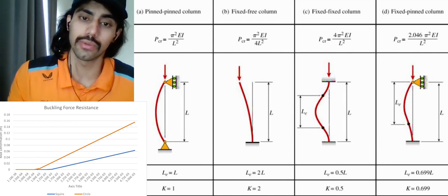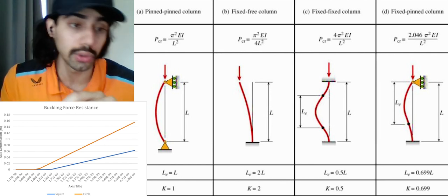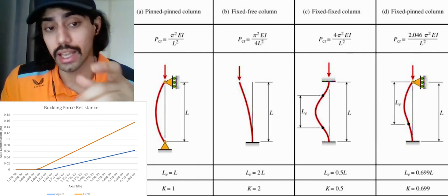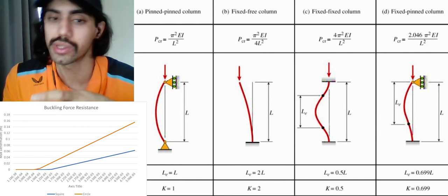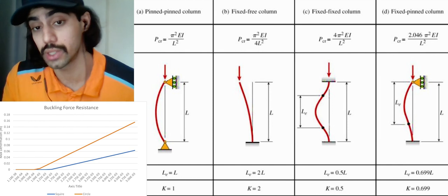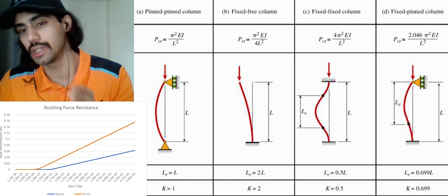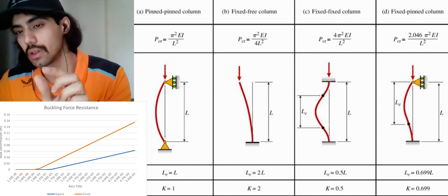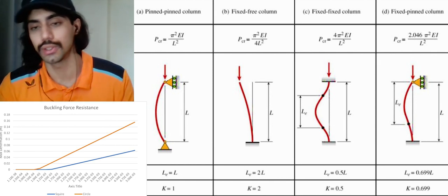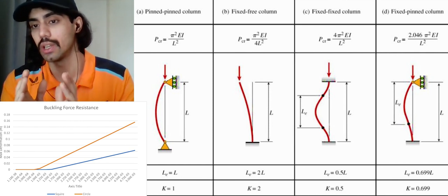We examine our profiles in an Ansys explicit dynamic environment because we aim to simulate real crashes over time. We set the collision velocity to 50 meters per second and the time interval to 0.005 seconds. I know it's a very small interval time, but we want to survey the end of the crash frames.